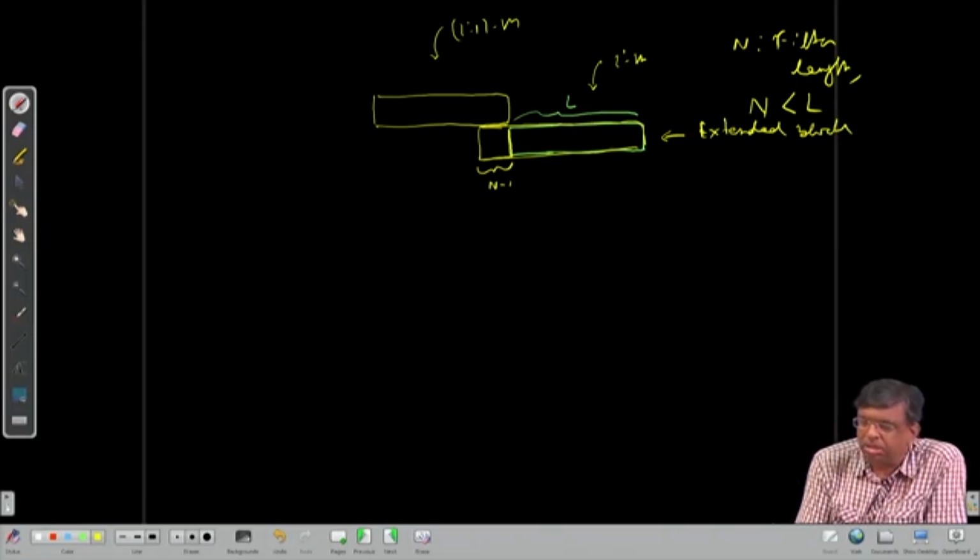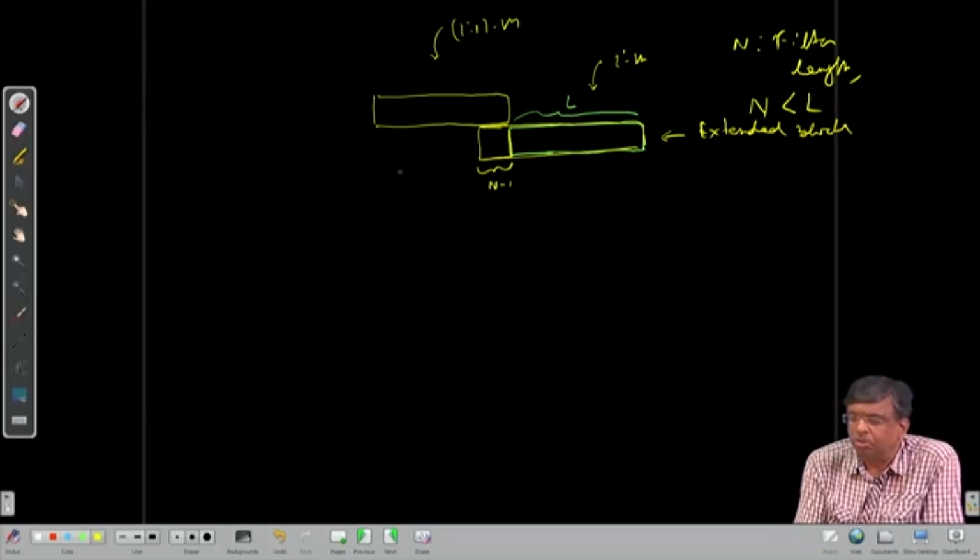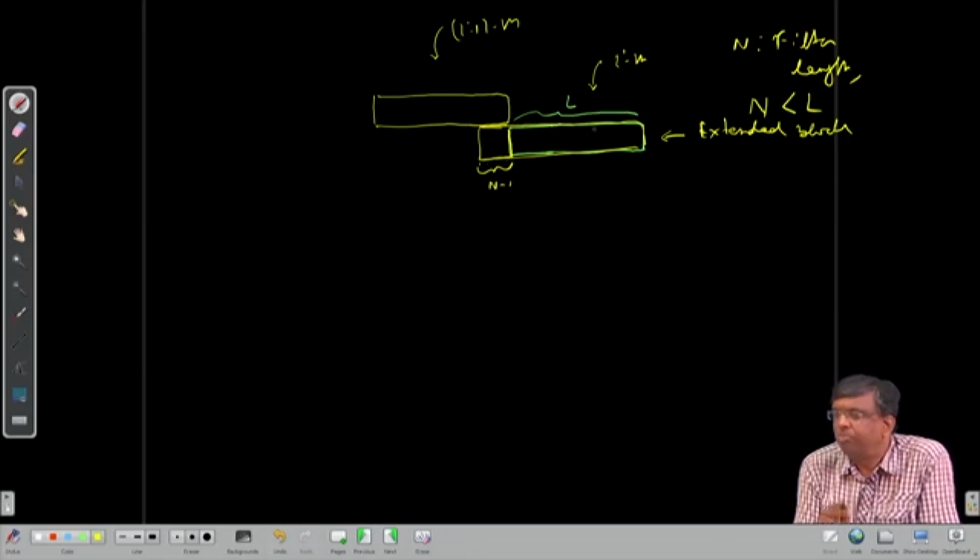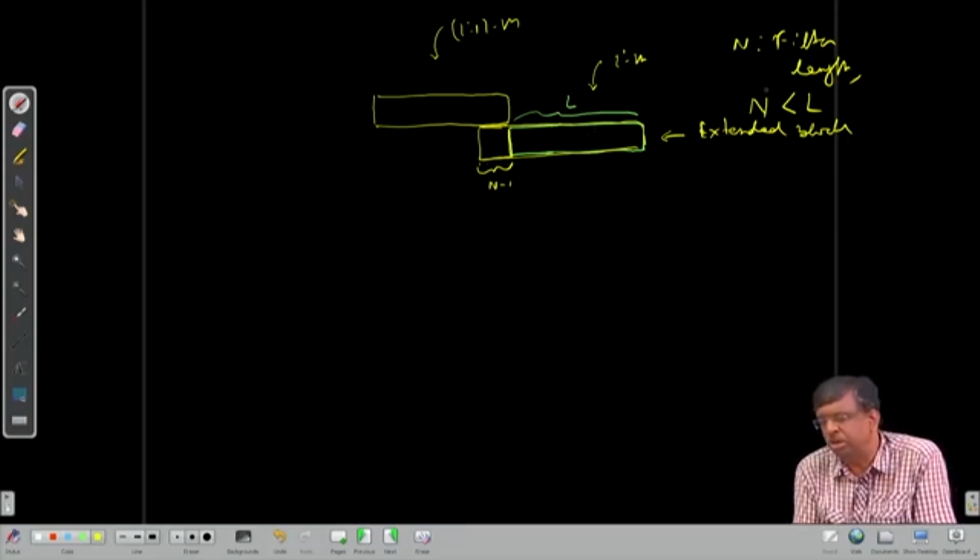Here I take this block separately, convolve the data here with the particular filter coefficient vector for the ith block, which is fixed for the this ith block or ith extended block. But then I discard the output here and take output from here, find out the output error, that is desired response minus filter output from this point onwards. Keep them for the update, for updating the weight vector from ith block to I plus 1th block.